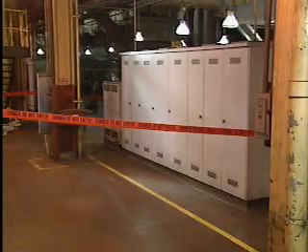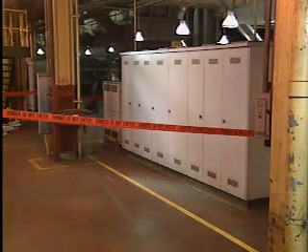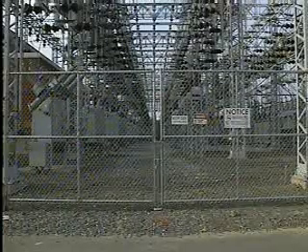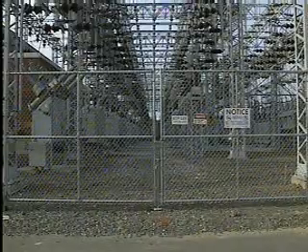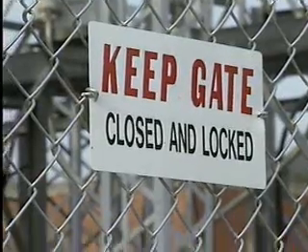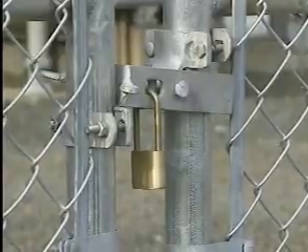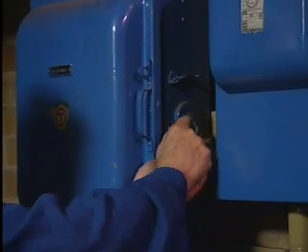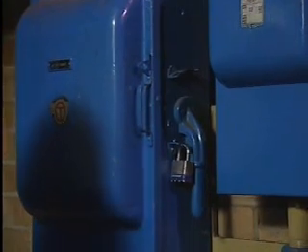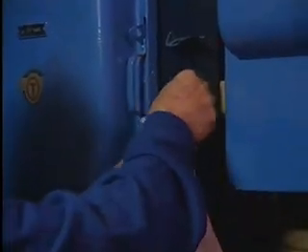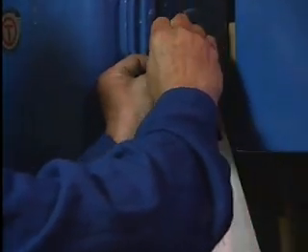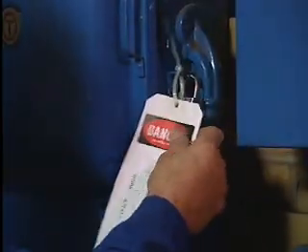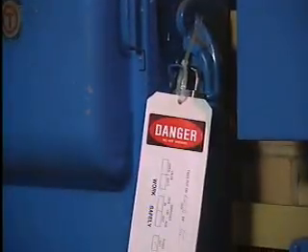In some situations, the barrier consists of warning tape around a work area. In other situations, hazardous equipment may be enclosed in an area surrounded by a fence or a wall. Access to the areas within barriers is usually restricted as indicated by locks, tags, or signs. In addition to helping prevent accidental exposure to hazards, locks and tags are also used to prevent control mechanisms from being operated by mistake. In other words, they provide a positive means of controlling hazardous energy sources.